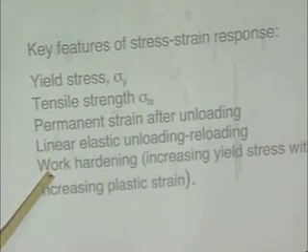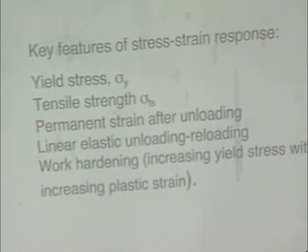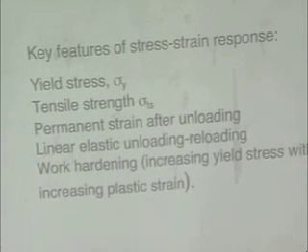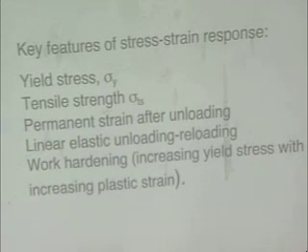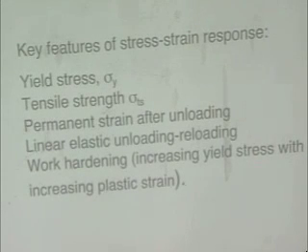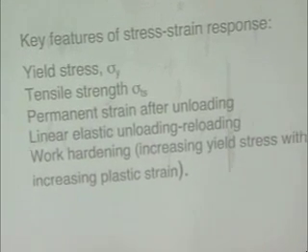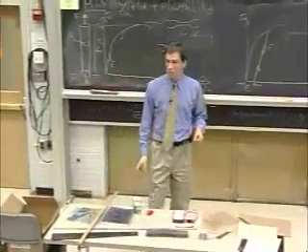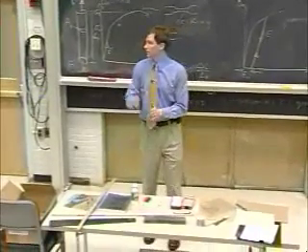And then once we go beyond yield, initially, we get this increasing strength with more deformation. And this is so-called work hardening. So increasing yield stress with increasing plastic strain. Any questions? Everyone buy that? Yes, David.